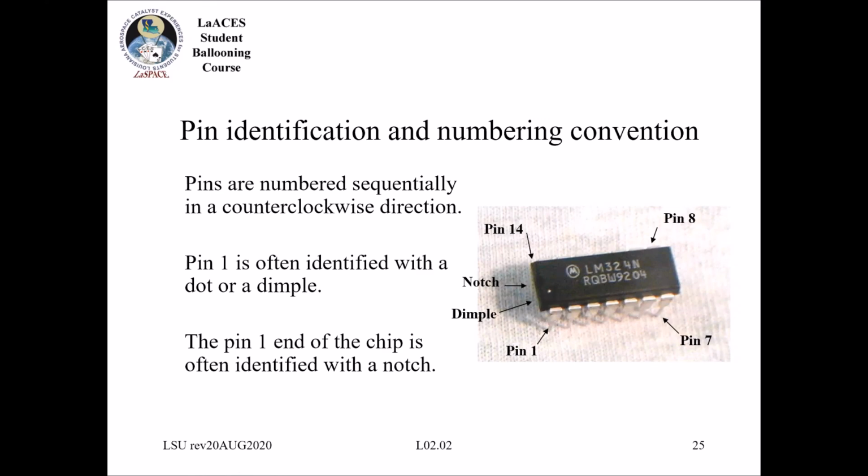But if you put it in backwards, you can imagine that 2 of these pins have a ground, another one has a voltage, and unfortunately, they don't make these reversible. So if you put this in backwards and the voltage and the ground are in 2 different pins than they should be in, the device will fail. And it also doesn't help that some chips, depending on the data sheet, always read your data sheet, will have multiple grounds. It just takes one of those grounds being connected to power for your chip to be fried.